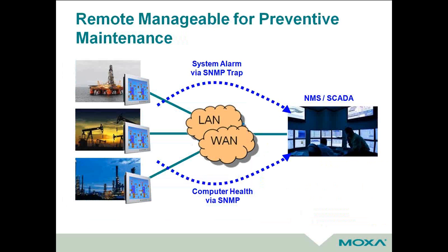We're going to touch upon this a little bit earlier. Now, you want to have an embedded SNMP system in the computing unit that allows for those remote diagnostics to feed back to, say, a central control room. And as I mentioned, that's not only important for you to have access to what that HMI is controlling in the field, whether it's an oil platform, drilling station, or a drilling rig.